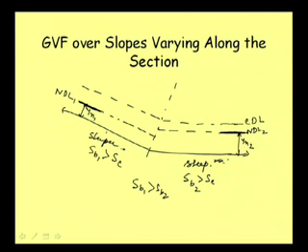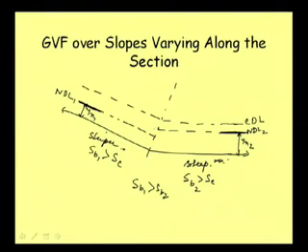Now in case of supercritical flow, as we know, control is at upstream, not at the downstream. So there is some disturbance in this portion, a change of depth, but this disturbance will not influence the upstream flow. So as it is, it will come straight up to this portion. It is not disturbing this one. Rather, this disturbance is not propagating upstream to influence this flow, that we have already discussed.